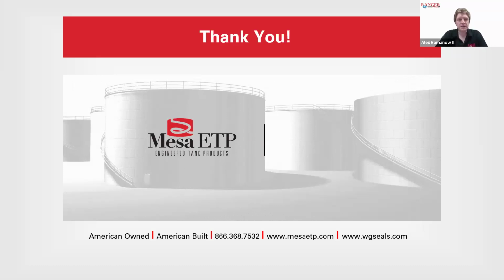There are a couple of questions coming up here, and one I'm curious about is, when we look at the measure in there, 25% is the fail rate on LELs or LFLs for your annual inspections. In our CCME code, it's 20%. Now, the gas testing method in our Canadian code pertains more to gasoline tanks. So when you want to explore other chemicals being stored, you actually have to do baseline testing for averages over a number of years.